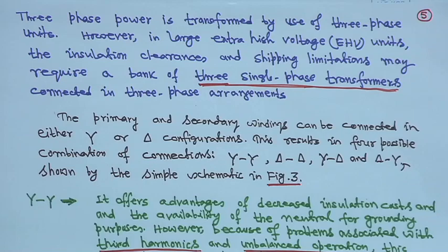somewhere, and you are carrying it some 1000 kilometers to some other place. If the transformer is made for 3 phase together as a single unit, it is very difficult to carry because the volume will be huge, but if you make single phase ones and connect them, then transportation is easier, right.